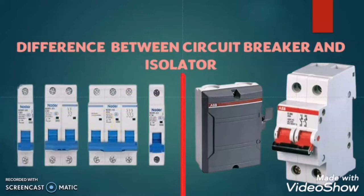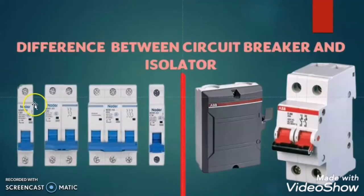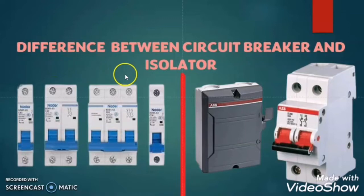So here I have some circuit breakers. This is MCCB, this is air circuit breaker, and in my first slide I have shown you the MCB, that is miniature circuit breaker. On the other side, I have shown you different types of isolator or disconnector. These types of isolator you will find in the substation or in high rating switch yards. And these types of isolators you will find in the LV sections, like in commercial buildings or residential buildings. Now let us try to understand in a simple way what is the difference between the circuit breaker and isolator.